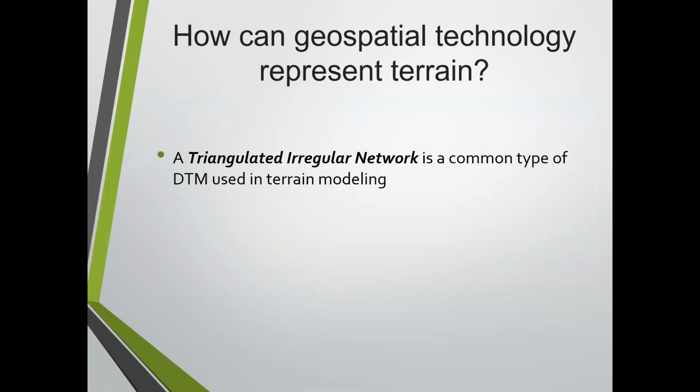When we talk about the concept of DTMs, that's just a general catch-all name saying I'm portraying this digital model 3-dimensionally in some way. But there are different ways of creating DTMs. The primary two sources are what we call the triangulated irregular network, or TIN, and what's called a DEM, a digital elevation model. You kind of have those two, and we can actually use them both in a lot of software.